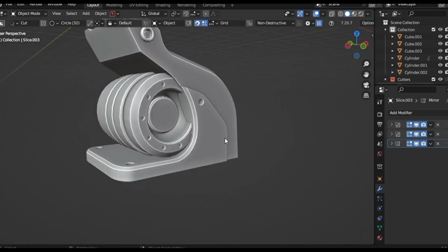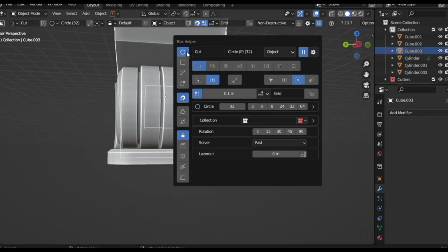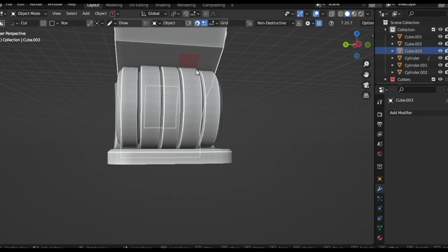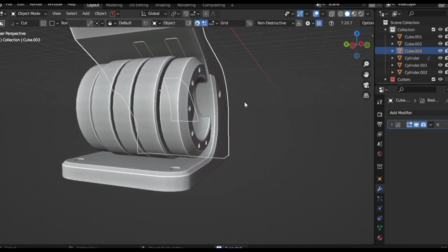See how our small chamfer changes the entire appearance. Moving to the back, let's run a box cut, something like a rectangle. Press B for small bevel, T to solidify and V to apply an array. Increase the count, adjust the separation and maybe a duplicate works best. Place it and confirm the cut.